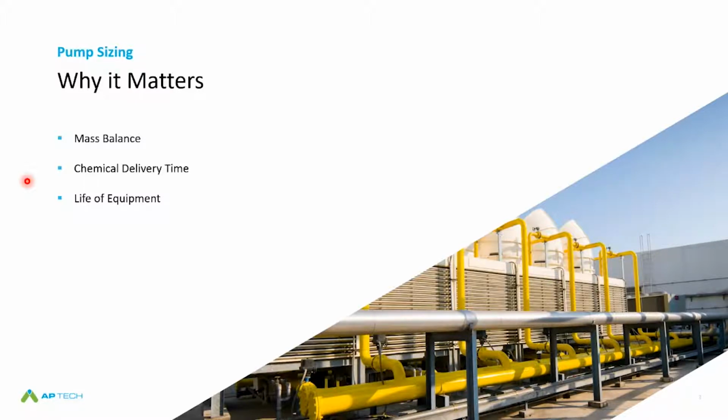The other part is the life of equipment. In the electronic world, there's a thing called duty cycle. Duty cycle is very important to take a look at, because that is basically a spec on that pump, telling you what that pump can do for how long in a certain period of time. Usually it's a percentage, and you typically want to stay on the lighter percentage of duty cycle, staying within like the 30% range of that pump.